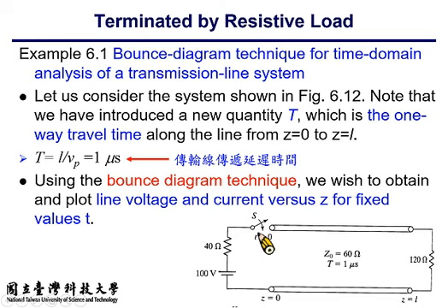Okay? And here, as the figure suggests, the characteristic impedance of the transmission line is 60 ohm. The termination is 120 ohm, and the internal resistance of the generator side is 40 ohm. And the generator, which is a DC source, provides 100 volt.